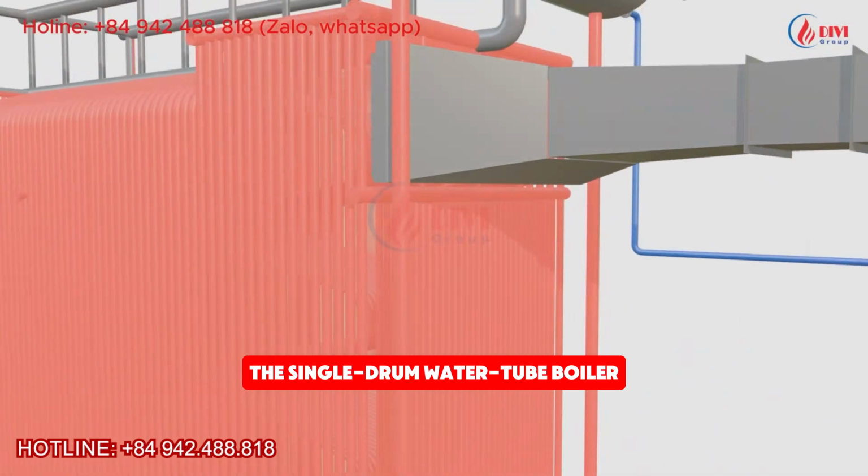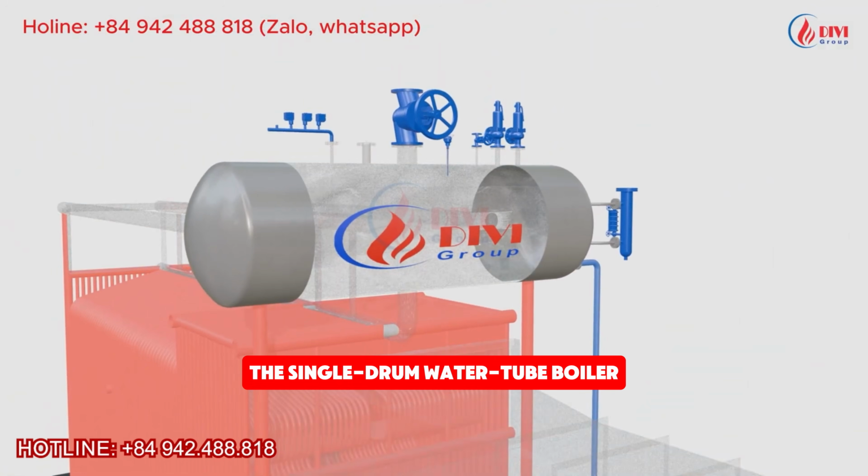Water flows from the drum into the generating tubes, where it absorbs heat and becomes a steam-water mixture. The mixture then returns to the drum, where the steam is separated from the water. Because it contains less water, this boiler can generate steam more quickly and usually has a shorter startup time.